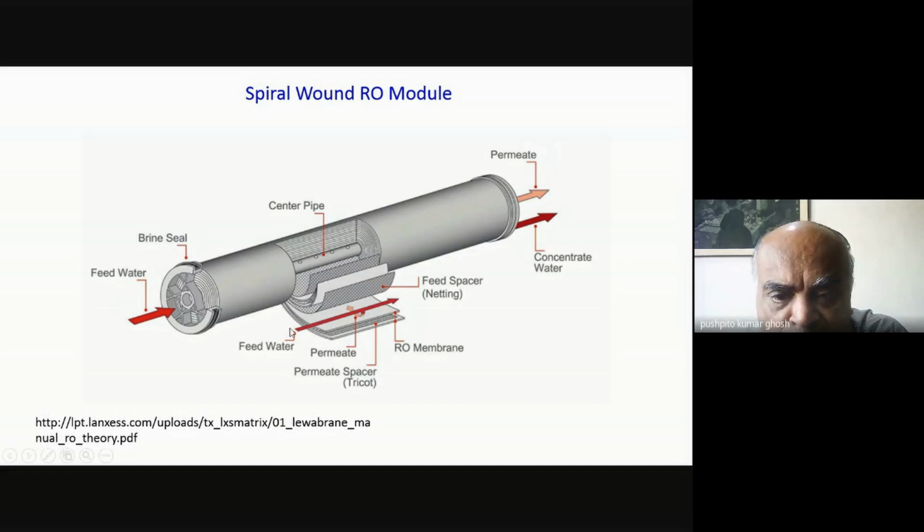What it does is that you have got your membrane, and between two membranes you have to put a spacer, and likewise on the back side of the membrane also you have to put a spacer. One is called the feed water spacer, the other is called the product water spacer or the permeate water spacer. This is also what is important to prevent the compaction, because you need a pathway for the water to flow. So you have to create some space for the water to flow. That's what the spacers do. And this configuration is very interesting. It's called the spiral wound configuration.